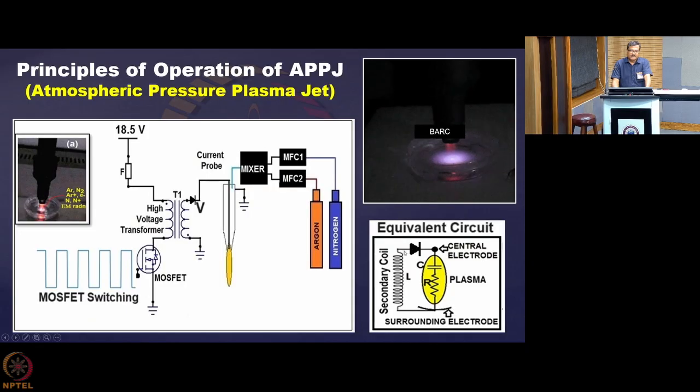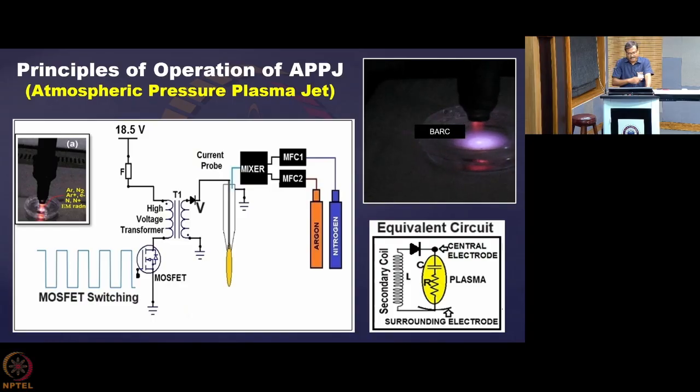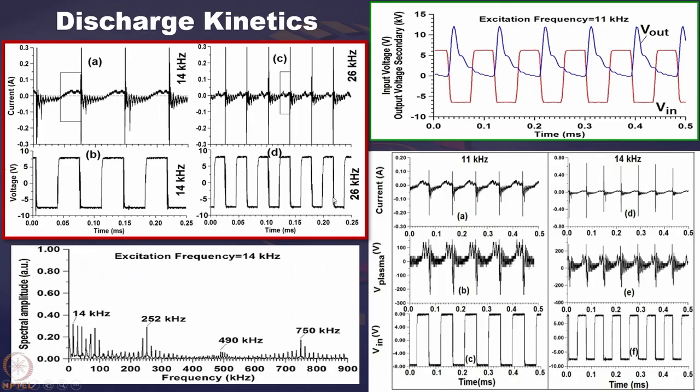What happens then is that the plasma is off because you are not applying any external energy. But the radicals already generated are there, so they are now getting collected by the electrodes, and that forms a current in the reverse direction. The electrons get collected very fast, then the ions come. So you are seeing two humps, which basically represent the kind of particles getting collected.